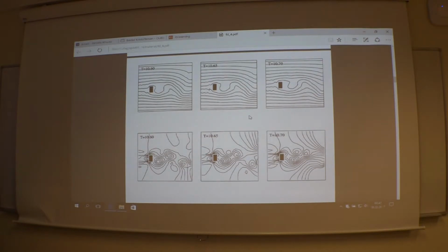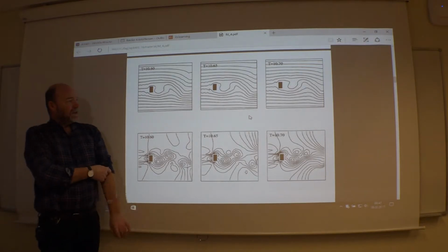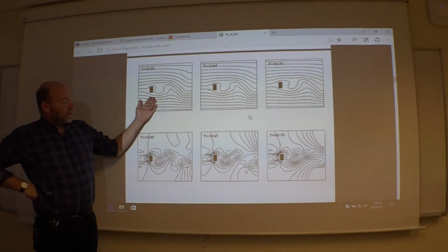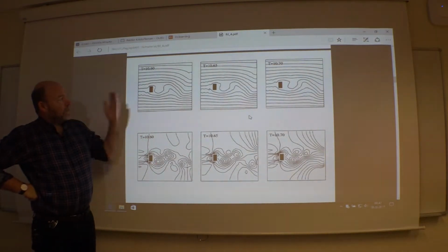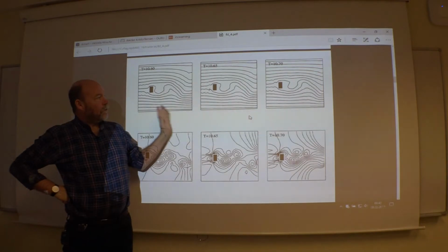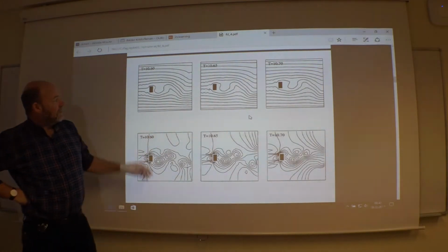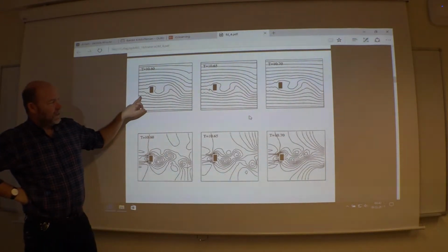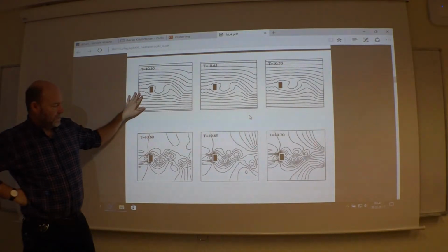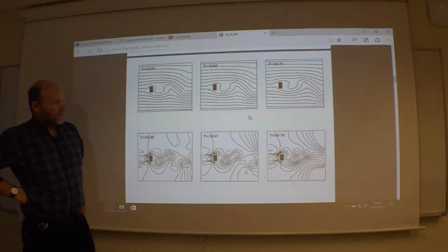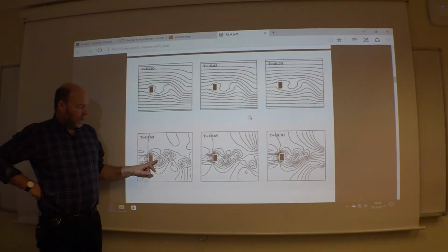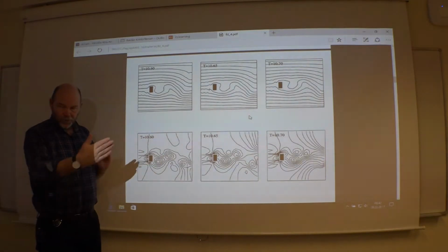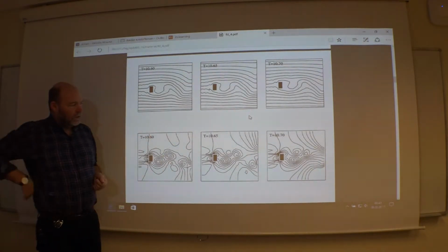So then you have an option of how to plot your results. Here streamlines, here isobars, and as time goes by they have a changing pattern. Here you see the streamlines again, indicating not so well resolved here in front, but okay. The isobars, you will have low pressures inside these alternating vortices, of course.